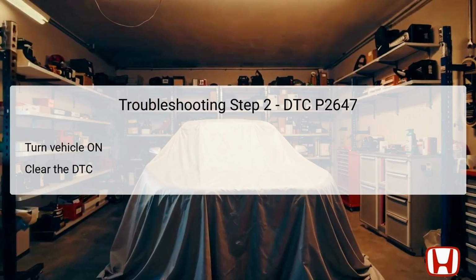In the second troubleshooting step, begin by turning the vehicle to the on mode without starting the engine. This mode enables the technician to run diagnostic tests without the interference of engine operation. Once in this mode, utilize the Honda Diagnostic System, HDS, to clear DTC P2647.